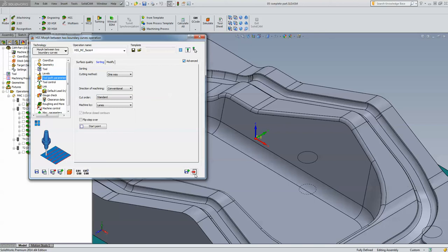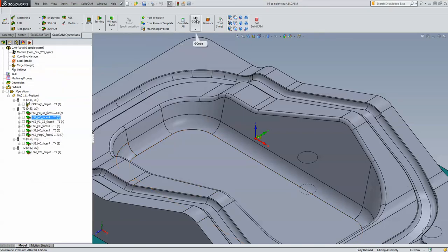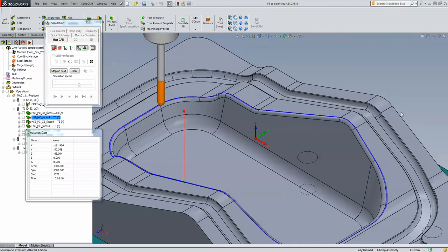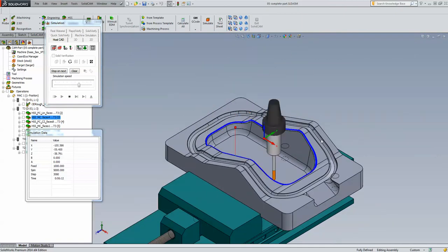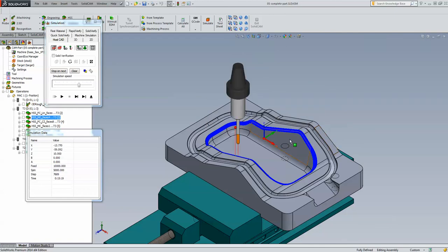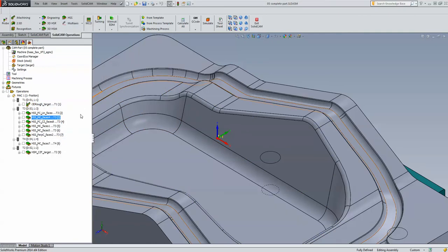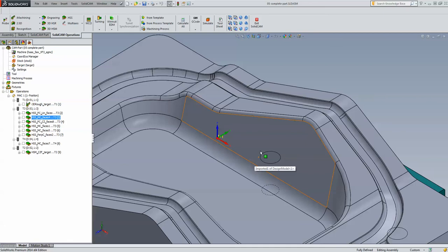Okay, taking a look at the actual simulation itself, you'll see that the toolpath goes around and around that part, machining exactly the way I wanted it to machine that part. Really good, efficient toolpath for those particular surfaces over there. Now, I'd like to continue actually down now on these walls over there, also using morph between two curves.